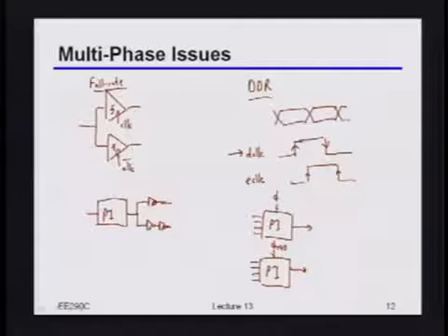Mismatch. Yeah, mismatch, right? So the obvious one is that first of all, even if they were all the same phase interpolators I had before, they're going to just burn more power, right? Just linearly with the number of phase interpolators. Now, that's not exactly true because the frequencies maybe aren't fixed, but roughly speaking, power and area goes up, right?